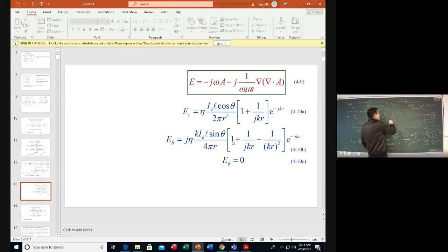K is equal to 2 pi over lambda, and R can be lambda over 2. So Kr equal to 1 is really a region where, for example, if you look here for E theta, the magnitude of the 3 terms that you can see inside the parentheses will all be equivalent, right? Because the phase can be different, because we have 1 over j in the second term, but the third term will be a pure 1, okay? But the magnitude will be comparable.